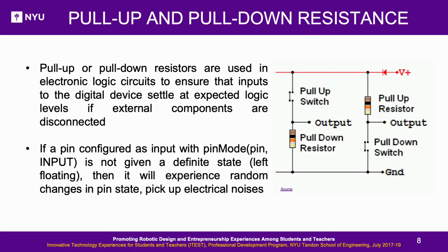In this case, the pin can randomly toggle between low or high. Pins can float because they do not have a well-defined voltage signal input. Things like external noise can arbitrarily take both values. You don't want the pin to float. So, you usually want to put a defined signal on a pin so that its state is known exactly. That way you know for sure if it's low or high. That's exactly why we use pull-up and pull-down resistors.